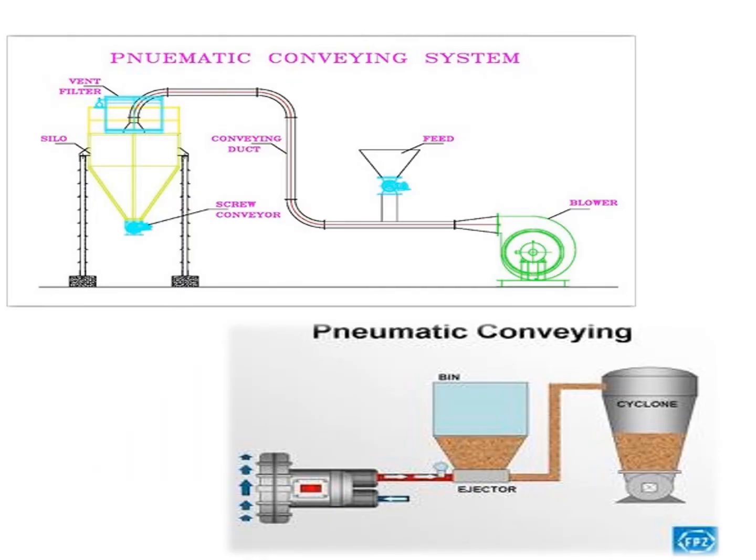This is the simplified diagram of a pneumatic conveying system. Different pneumatic systems are created for various transportation methods. The energy required to move material through a pneumatic conveying system is supplied by pressure differential and airflow. Here, the pressure and airflow used in the conveying line are generated by the system's air mover, which determines whether to generate pressure or vacuum to convey the material.